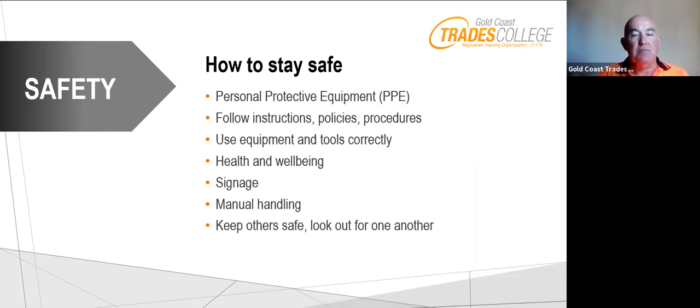Manual handling: be aware you may be lifting a battery, an alternator, some heavy componentry. You might be twisting or turning, lifting up, pushing down, all sorts of angles that you may get yourself into with different weights and components. Keep others safe. Look out for one another. That's your duty of care. Be very conscious of workplace health and safety as we work our way through this.